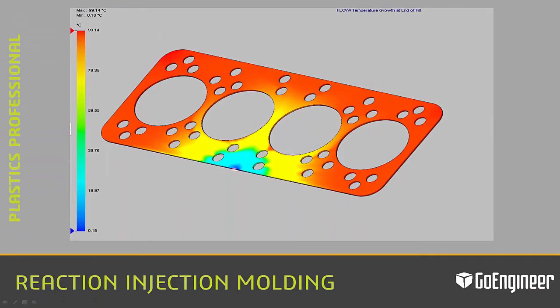Another study available in Plastics Professional is reaction injection molding. This is the process by which two reagents are mixed together and injected into a heated mold to react and solidify. Materials used in this process are classified as thermoset plastics. Once cured, thermoset plastics can have impressive heat and chemical resistance.